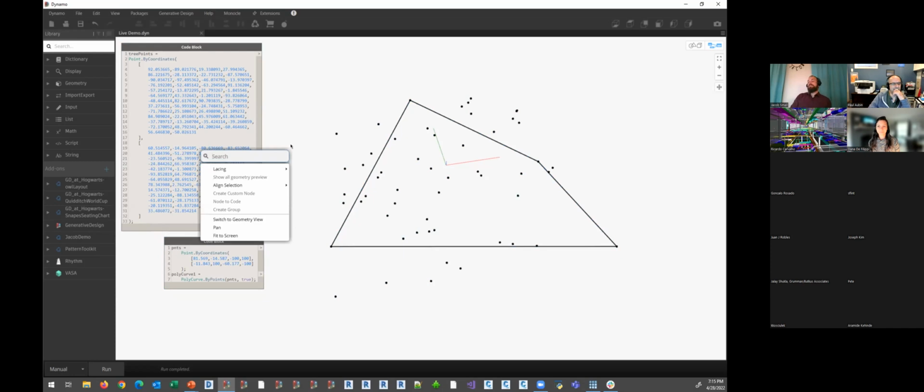Now, because I've done some work here in serializing some stuff manually into the graph, this step wouldn't have to be performed, but I want to make sure we understand it. I mentioned before that we're in Dynamo Sandbox when we send stuff to generative design, so we have no access to the Revit API. Notice no Revit, no AutoCAD, no Civil 3D, no FormIt over here, just Dynamo Core, and that's it. So if your data came from somewhere else, you can't tell Dynamo to go grab that data again.